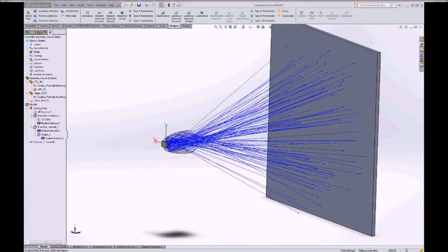So if we look at the Analyze tab here, just like when we were looking at the source, we can get numerical data. Where are all of the rays? What's their power and what is their position and direction? We can get irradiance, power per area information, intensity, power per angle, and we can get it in direction cosine or angular space. We can also, if we had a polychromatic source or dispersing components, do photometric type calculations as well.